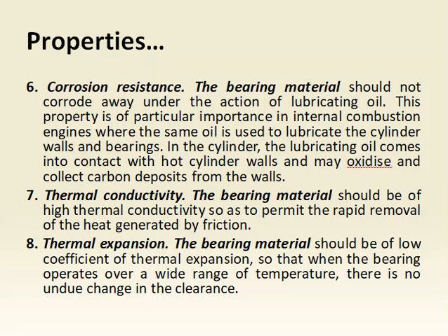The thermal conductivity, next property. The thermal conductivity of the bearing material should be high, so that it provides rapid removal of heat generated by friction and maintains a uniform temperature of the material.